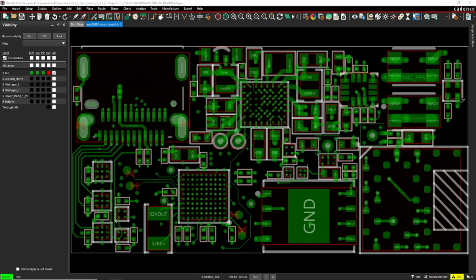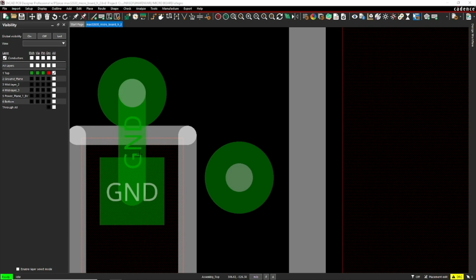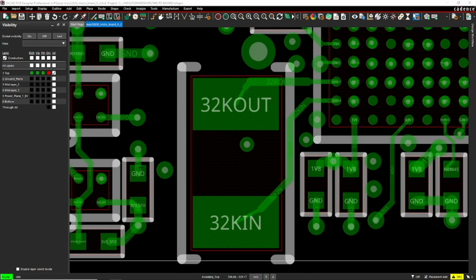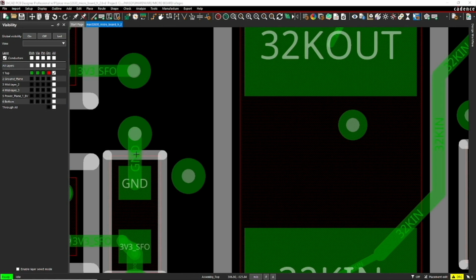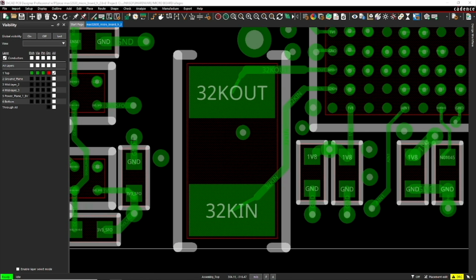You want to route as many traces to ground reference as possible, especially on chips. And see, each of these capacitors has a route to ground as short as possible. These are called fanouts. Why would we do this? Because that greatly reduces the inductive loop from any pin to its return path to ground. Minimal loop inductance causes minimal impedance, then a lower chance of issues for any given chip or device or PCB.